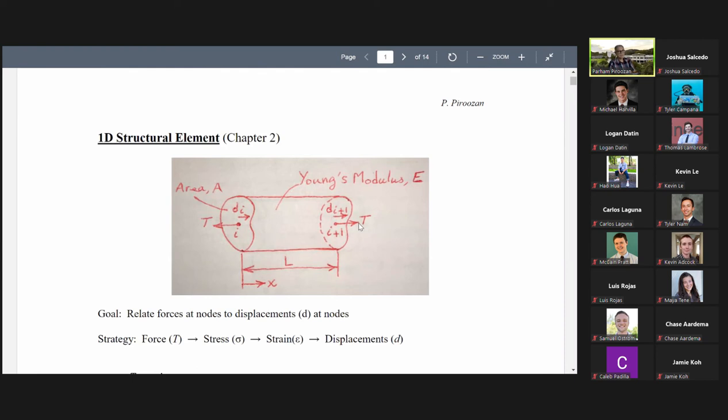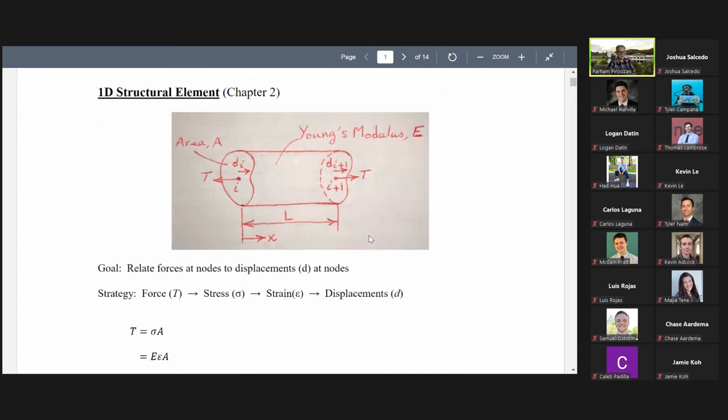In experimental mechanics, sometimes we use Moiré techniques, or we have very sensitive techniques that even with a very thick bar, we just touch it with a finger and we see that these fringes move, which means that it deforms exactly like a spring. But this spring is different, it's just large because of E. But the behavior is the same. So we treat it as a spring.